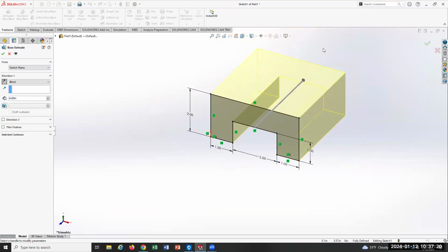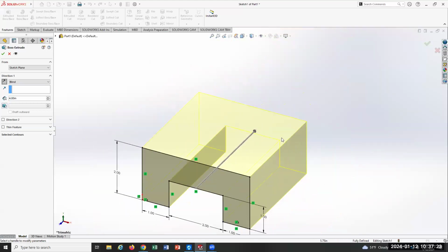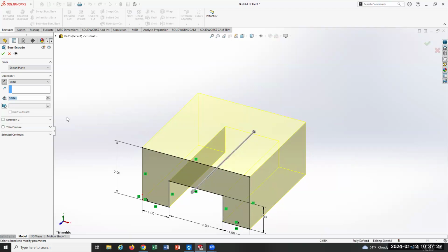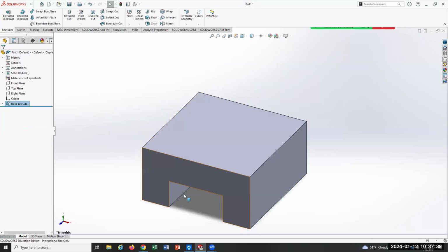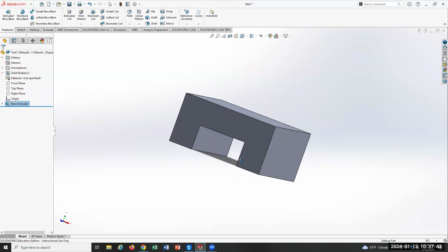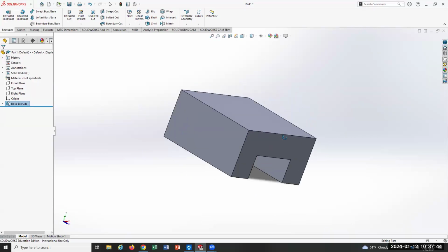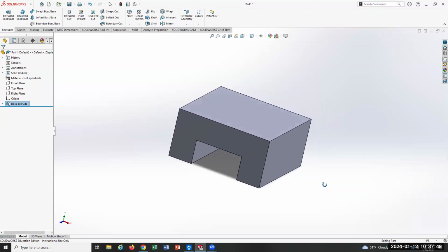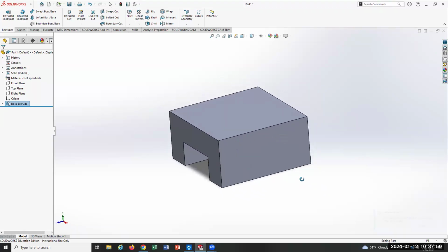Okay. Now there's things you can do here. Like if I grab this arrow, I can drag it around. Well, that's just not very accurate. Now it's 395. So I prefer the input method. I used extrude, so it's making a solid. Green check mark, and I can look at it. Whenever I do this move, I always roll it around, and that is pushing the roller mouse down like a button, and then moving the mouse, okay?